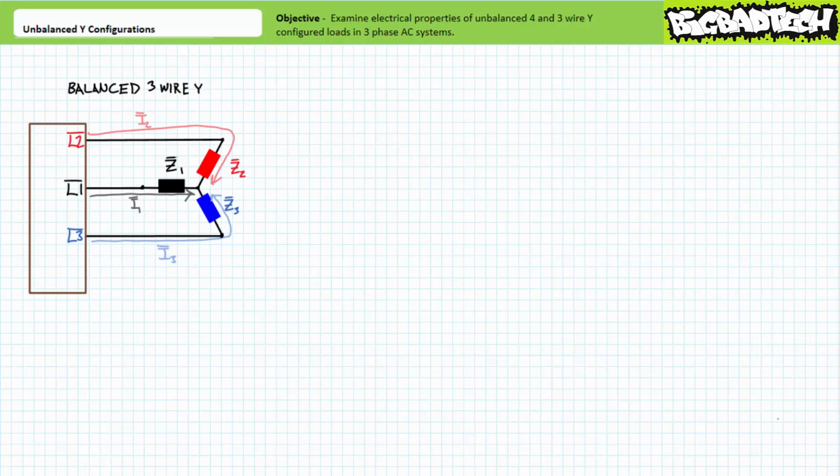Do a single Ohm's law calculation, then appropriately phase shift it for the remaining phases. Then do a single AC power calculation using only the relative phase shift between voltage and current and multiply it by 3 to get the total power. Move on. You'll be absolutely overjoyed to realize that most circuit analysis scenarios involve balanced load configurations, including common industrial applications like shop heaters and industrial 3-phase AC motors used to drive pumps, turn fans, or perform other industrial tasks.